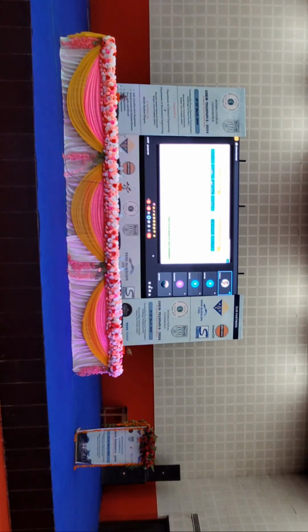For example, Honda Civic. There is a term known as the degree of hybridization, meaning how much hybridization we are doing. The degree of hybridization is defined as the ratio of the power from the electric motor divided by the total power from both technologies, one being the IC engine and the other the electric motor. If the degree of hybridization is 0, it is a pure IC engine based vehicle. If it is 1, it is a pure electric vehicle or a BEV. Otherwise, between 0 and 1, it is either micro, mild, strong or the PHEV.